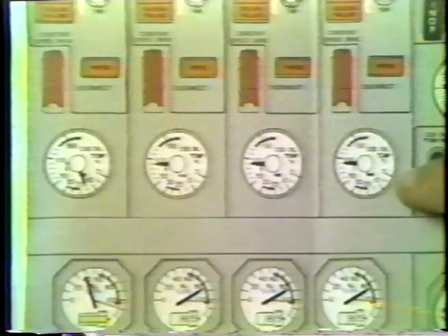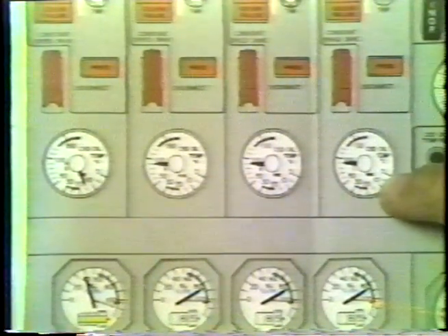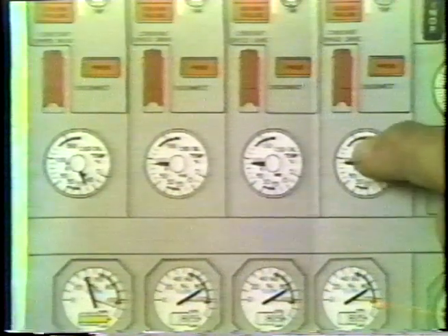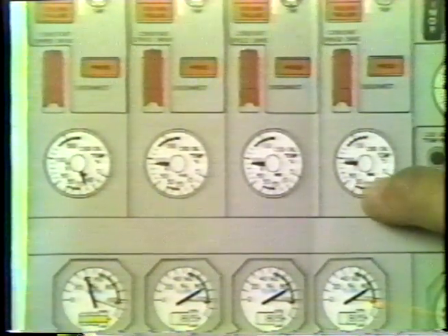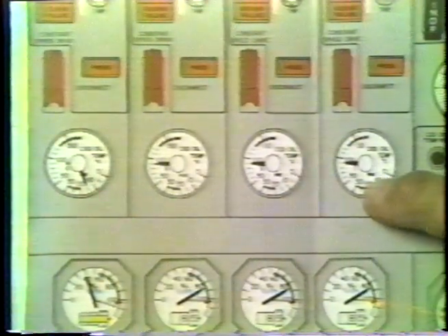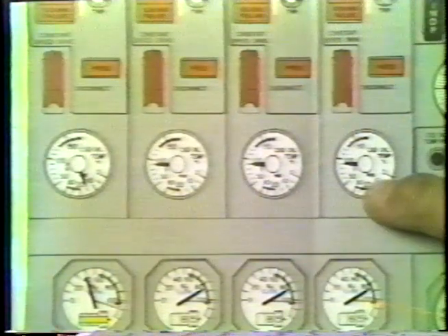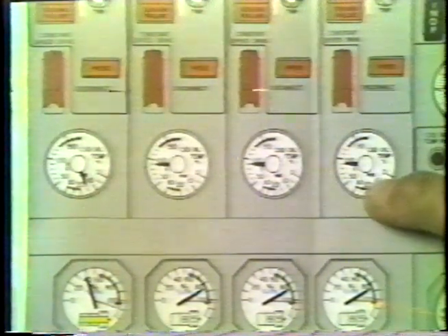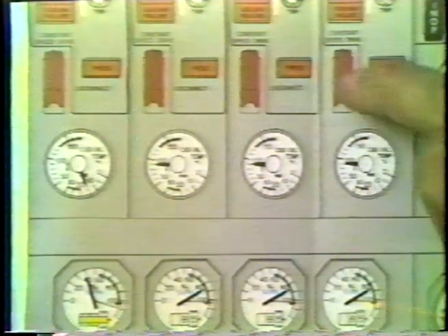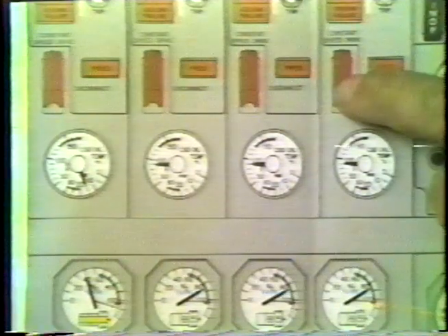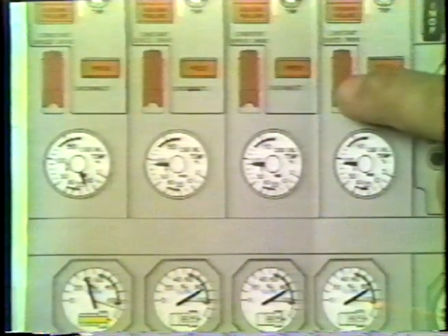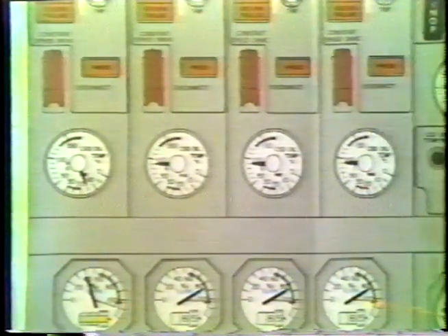The net result is when you're operating at too high of a temperature, either the out or the rise, imminent failure of the CSD is possible. To prevent this from happening, a disconnect switch, which is normally safety wired, located just above it, can be operated to totally disengage the CSD from the accessory drive.